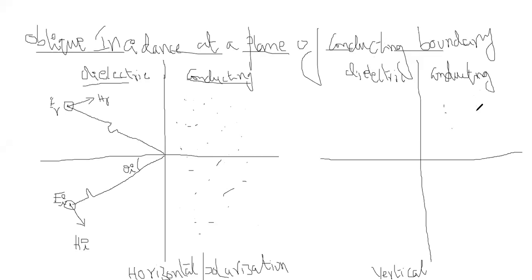There is some difference to indicate the conducting medium; here is a shaded part. Now see what we are saying about vertical and horizontal polarization. In horizontal polarization, the electric field is perpendicular to the plane of incidence, or otherwise the same electric field is aligned parallel to the boundary surface between the dielectric and the conducting. Vertical polarization is related to the magnetic field.